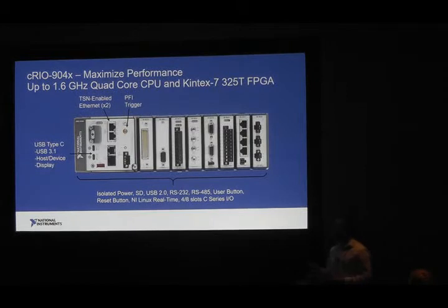Another one is the PFI trigger that you see in this upper portion here, which is something that if you've used a Compact DAQ controller chassis before in the past, you're probably used to. It's largely used for signal-based synchronization across distributed devices. As we integrate this new synchronization technology of TSN, honestly it was a big question of whether or not we include a PFI trigger line for synchronizing some distributed measurements, since we have this Ethernet capability.